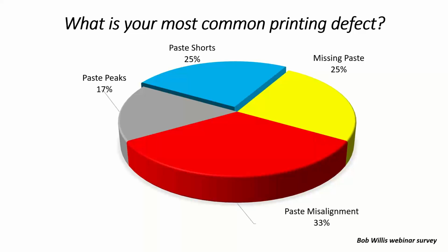And I can understand that because of the variability we can get with the PCB, regardless of whether we use fiducial optical correction, because if you've got boards in a multi, then your fiducial correction can only give you the best fit, not a perfect fit.